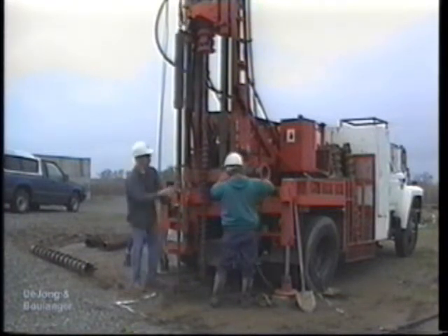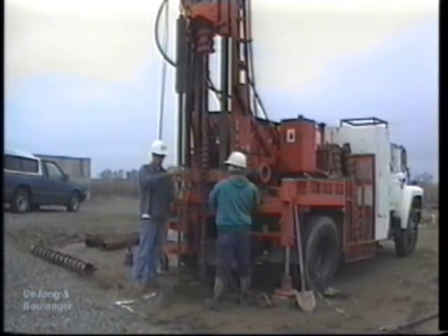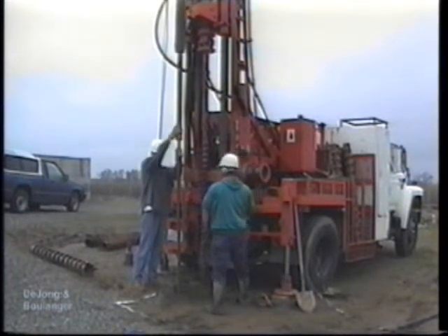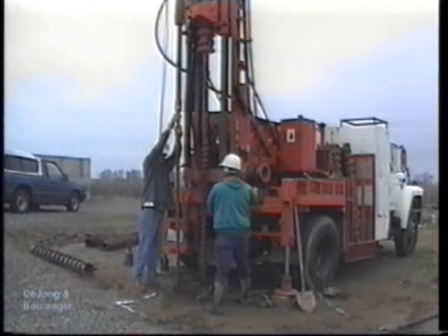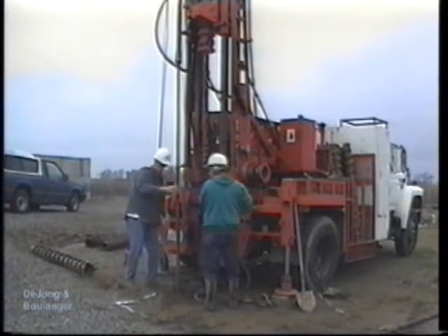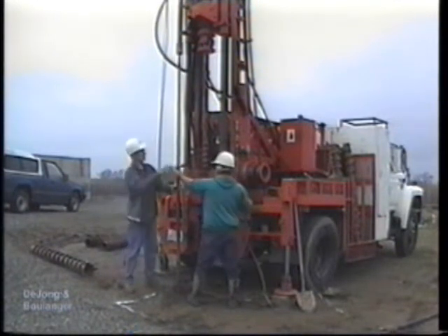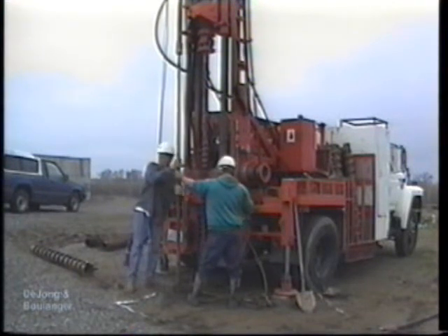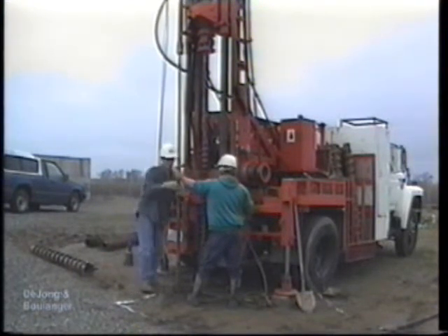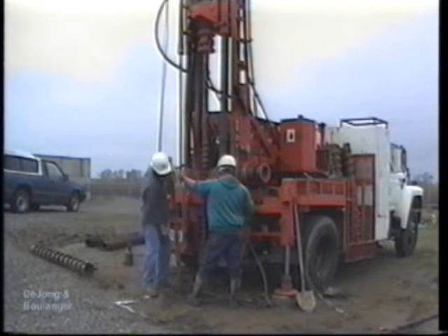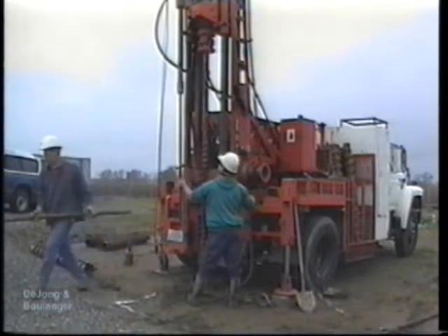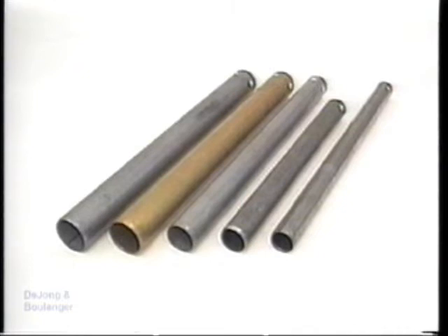The blow count rate, or number of times the hammer is dropped per minute, can also affect the N value. During sampler penetration, negative or positive pore pressures may develop in the soil. A low rate of blows will permit more of the excess pore water pressure to dissipate between each blow than can occur with a faster blow rate. The result is different effective stress and have difficulty retaining the sample.